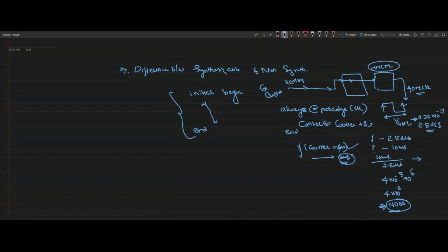Can you tell me what should be the bit size of this counter? What should be the size of this counter? Bit width, whether 5 bit, whether it should be 12 bit or 16 bit. 5-bit, I think. 5 bit can go up to 32, right? 2 to the power 5, that is 32. 0 to 32, but I want the counter to go up to 4000. 12-bit counter, sir. 12-bit counter. How did you find?